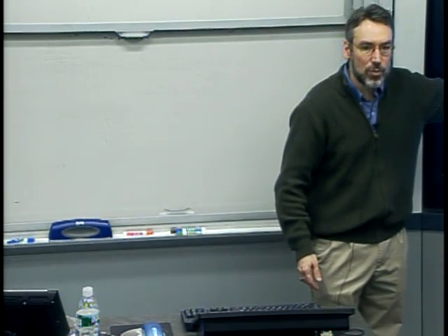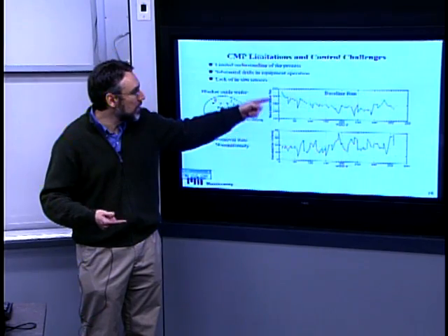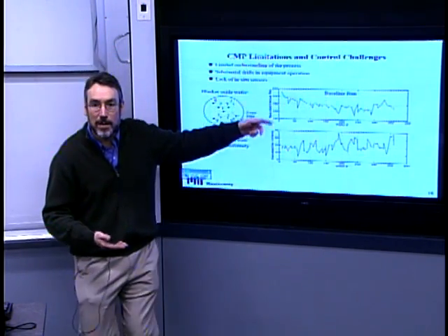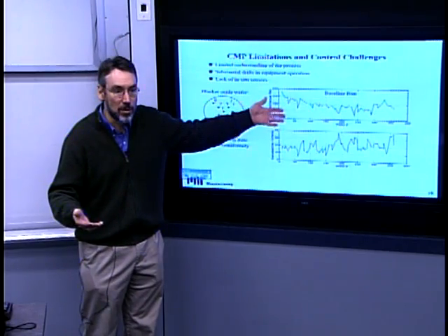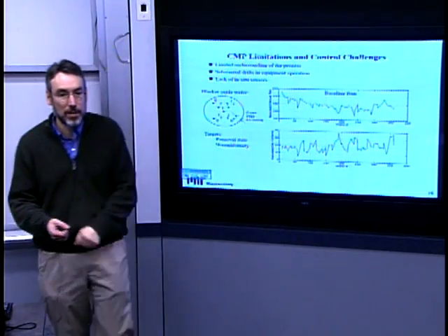So it actually ended up being a fascinating story, the adoption of CMP, because it was so counterintuitive of a process, exactly as you said. So we'll come back later to control strategies for dealing with this. Basically, with this kind of drift, you could start to think, well, I can measure this, and on subsequent runs, if my removal rate has drifted down, I'd like a strategy where I polish a little bit longer, or I press a little bit harder, these sorts of things.